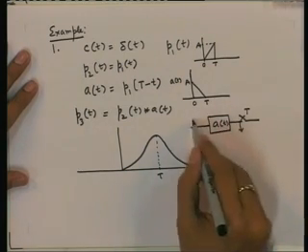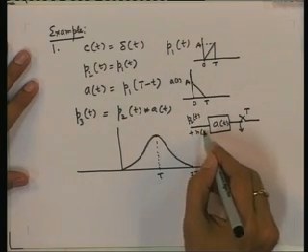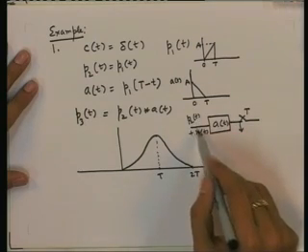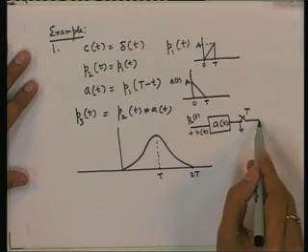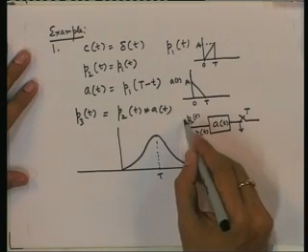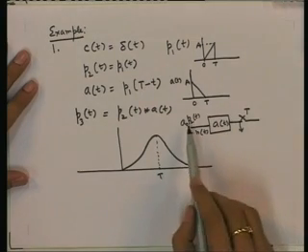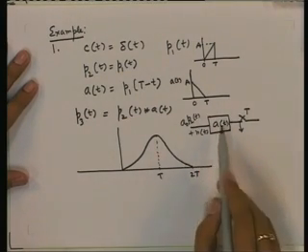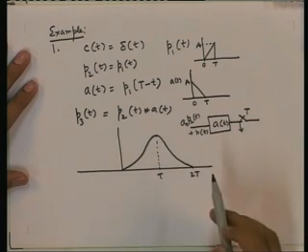So, here we have P2t plus noise, which we neglected, but we are actually receiving this at the receiver. Then we are passing it through the matched filter. What will we get here? It is actually A0 times P2t, the 0th symbol, with some scaling also there. So what we will receive here is P2t convolution At evaluated at capital T times A0.